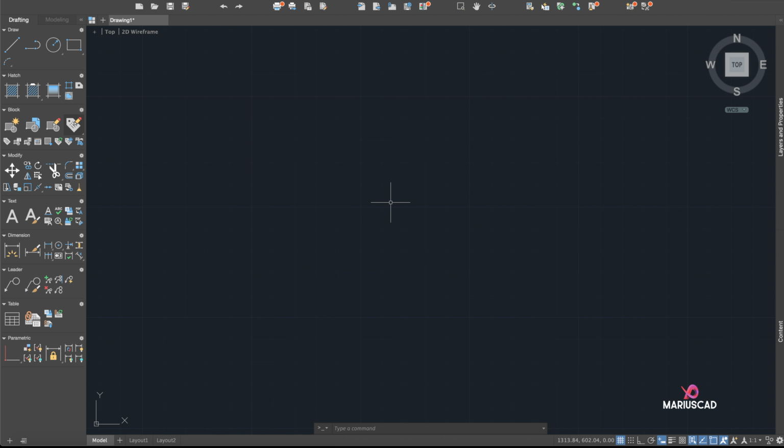So I will delete it and I will activate here the ortho command, or I can just type it. Okay, so now I can go with straight lines on horizontal part and vertical one. So it's perfect. And now before choosing the second point, I will type again 100, and I have a 100 units line here. Okay, and I can continue. I can press again line and go up in every part I want. It is not a problem.